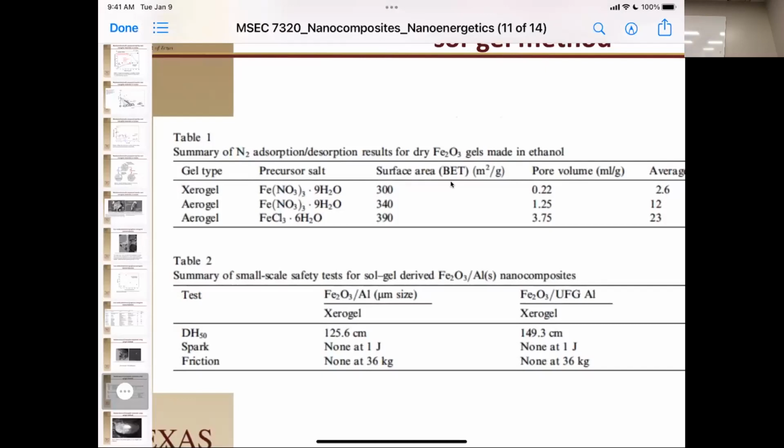But in friction, I would say, yeah, friction, you also can detonate things. Anything that breaks a crystal gives enough energy, or a spark. So in friction, we call that tribological detonation. And if you think about it, every time you break a crystal under shear, you're giving enough energy to detonate the material.